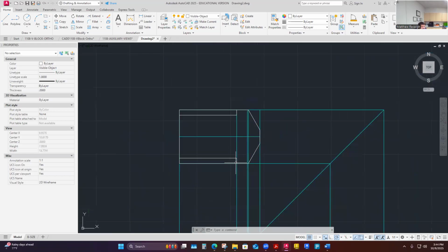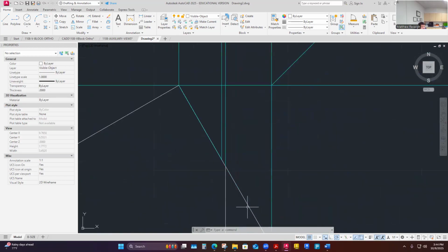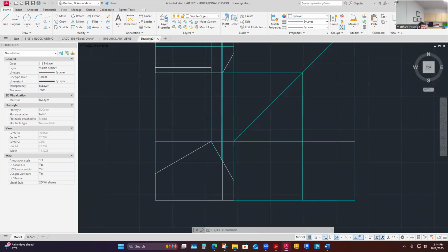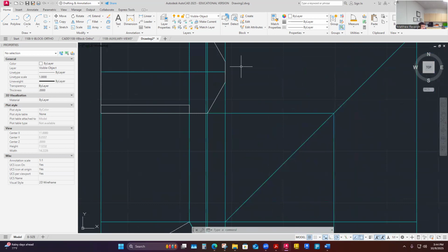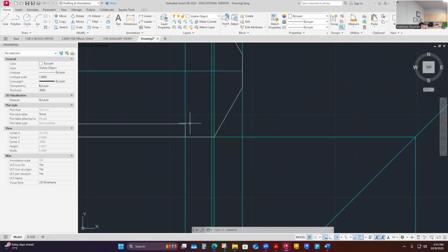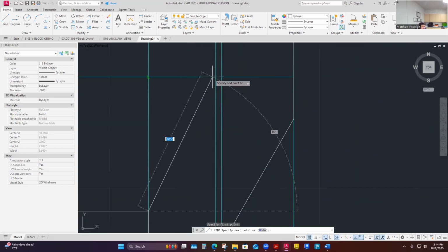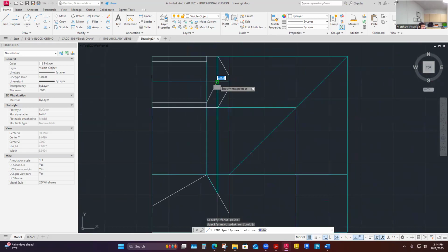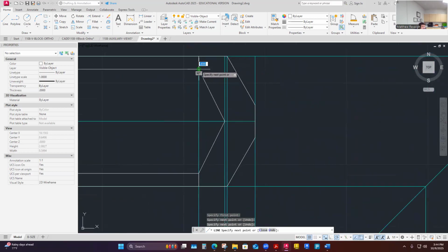And then maybe I'll be able to at least draw in the foreshortened line that goes down to the V because I have the depth of the V in the front view right there, and I projected it up. And where that intersects the center line that I put in, that point down to that will be that foreshortened line, part of this surface here. So I'm going to put that in now. Kind of got the point to point line up here. Point to point here, not the other one. That's a different feature. And then back up to the point here, right?